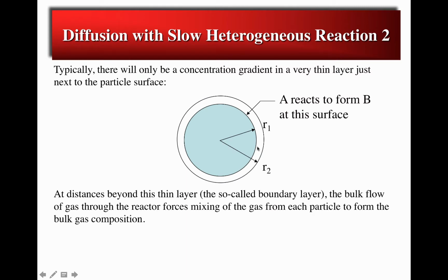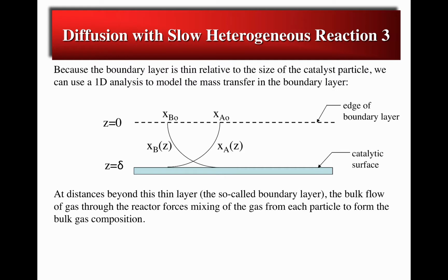We'll learn in Chapter 20, when we study boundary layers, how to predict the thickness of boundary layers and how to predict rates of mass transfer through boundary layers based on fundamental mass transfer concepts, typically dimensionless numbers like the Reynolds number, which enter the evaluation of the mass transfer coefficients in these cases. But we'll save that discussion till we get to Chapter 20.